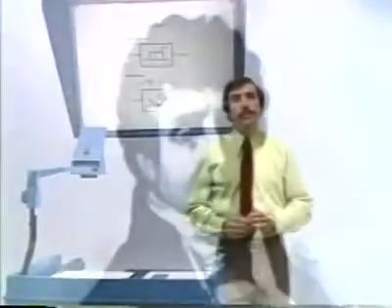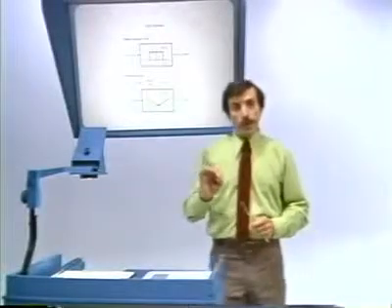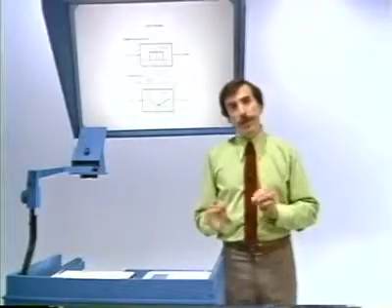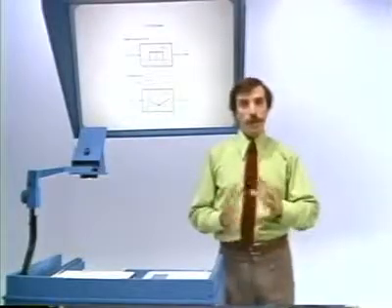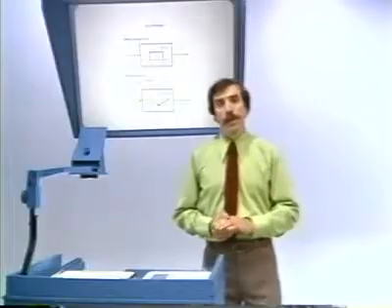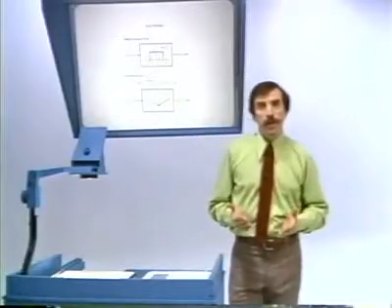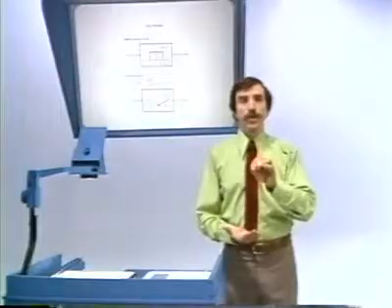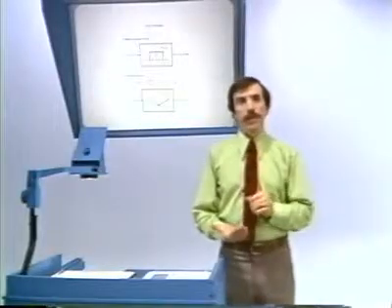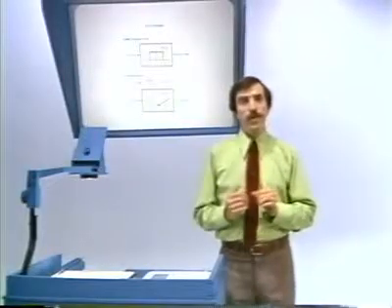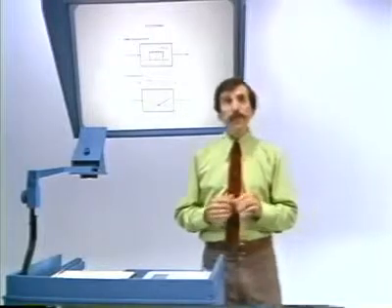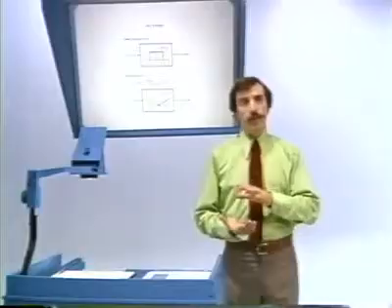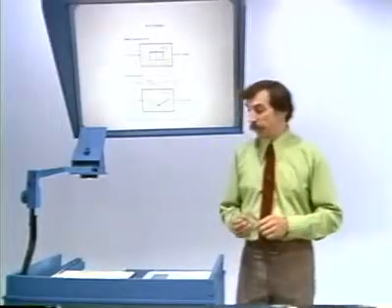Okay, now what we can also consider is what would happen if we looked at the differentiated image, and there are several ways that we can think about this. One is that a differentiator, of course, the output of a differentiator is larger where the discontinuity or where the variation is faster. And so we would expect the edges to be enhanced if, in fact, we differentiated the image.